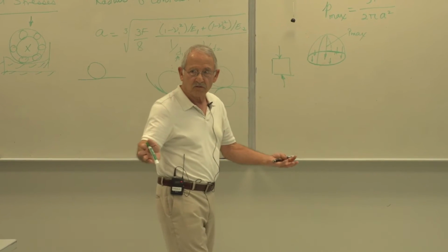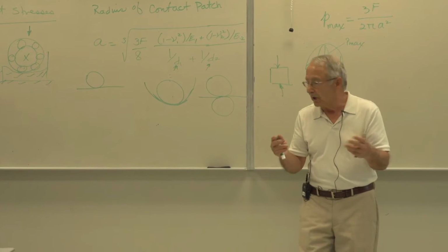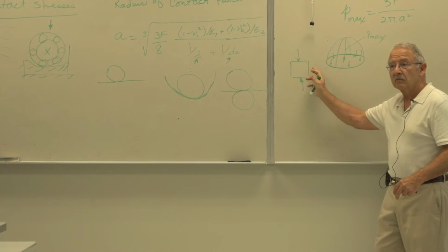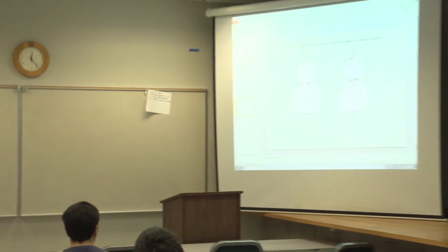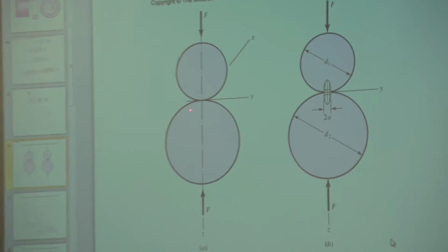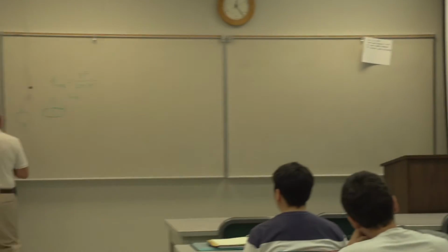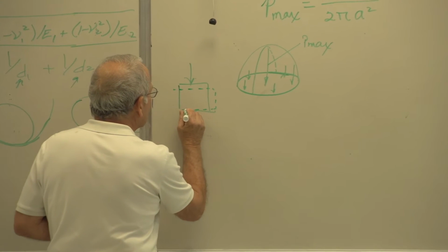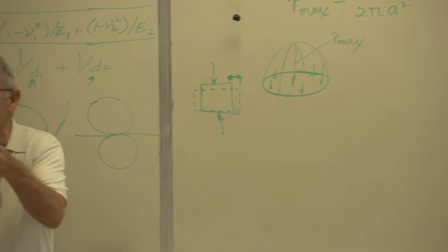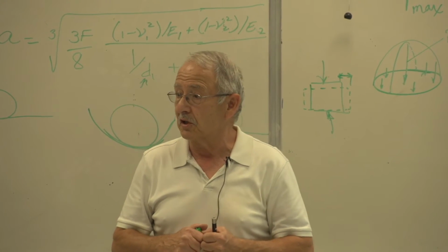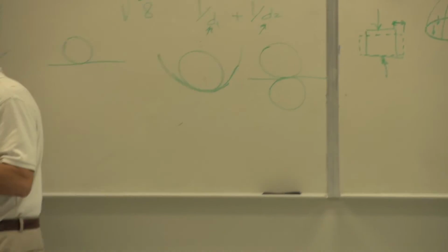Decreases. Okay, so that should be obvious. Is there any other change in any other dimension? Poisson's ratio, right? Okay. If there is nothing supporting this, this will grow laterally. But right here, here's the stress in the z direction, epsilon in the z direction, and then epsilon in the x and y direction. There's a whole bunch of material supporting that. So this change of length in this direction becomes tough to do, meaning there's a compressive stress preventing that change of dimension. Not that it doesn't exist, it does exist. It's just not as much as it would have been if this were free to change length.